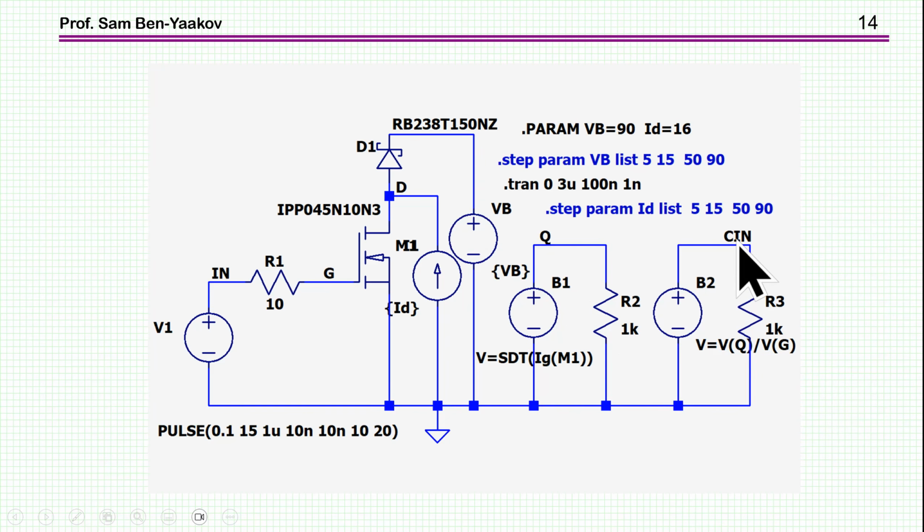This is now large signal. These are not the small signal capacitances that I've just shown in the plots, but the large signal: the total charge over the voltage. This will be the value that you'll compare to the value given by the vendor of the gate driver. They're giving, again, a capacitance. This is the capacitance which is relevant for this comparison.